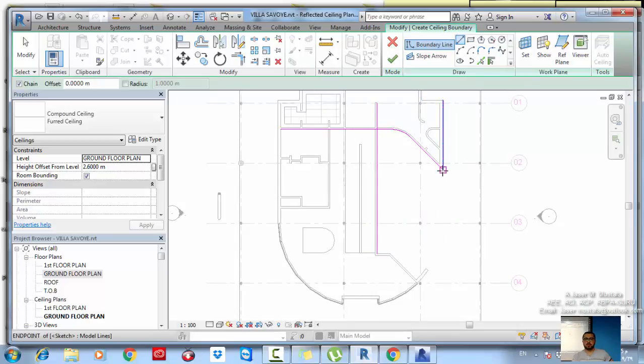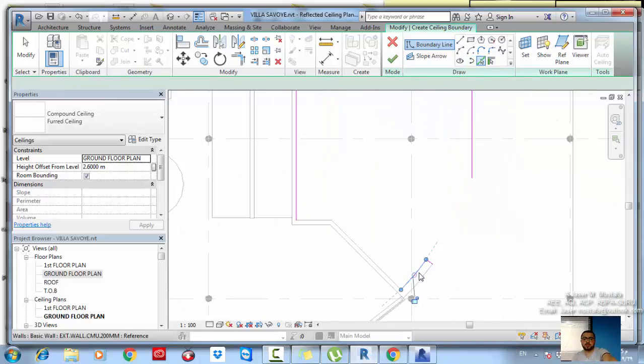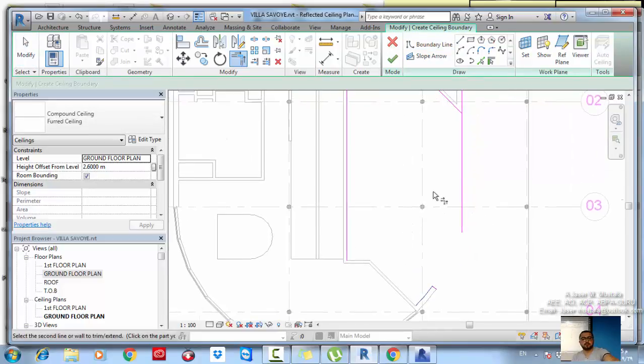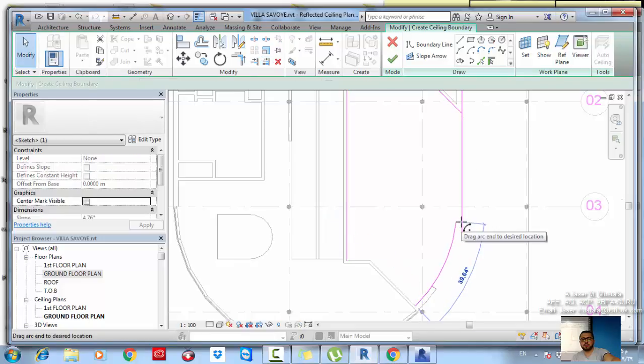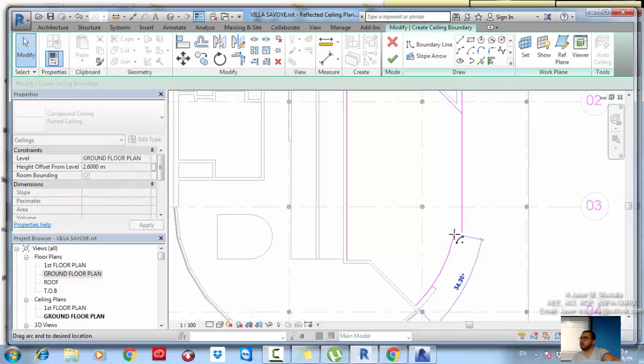We should have one here. And then pick line. Click, sorry, on this. Let's consider this is our ceiling. Extend. It's not extending. I select this. It's not intersecting. Fine. That's why it's not connecting.